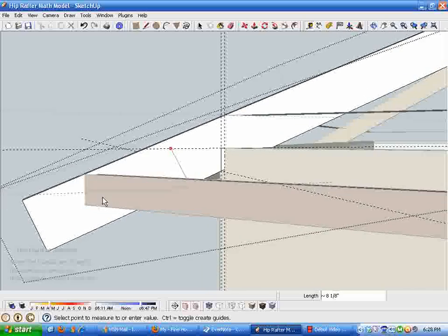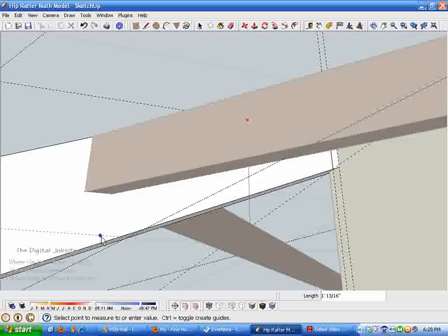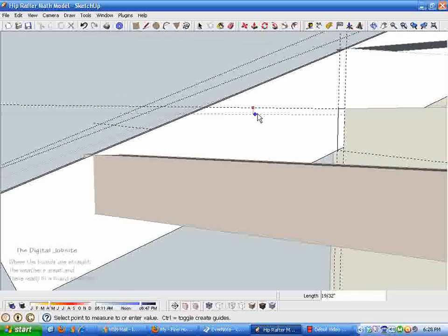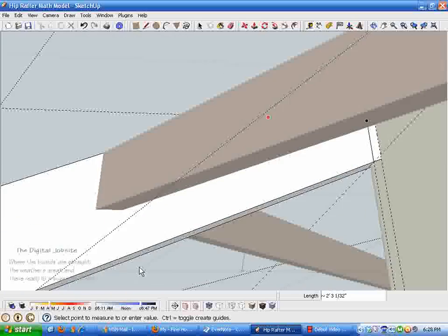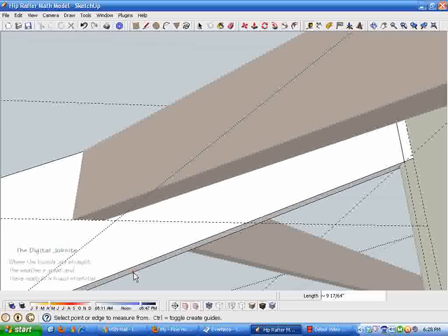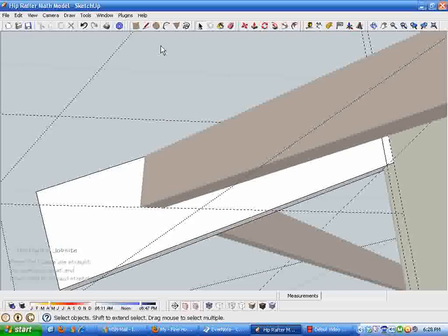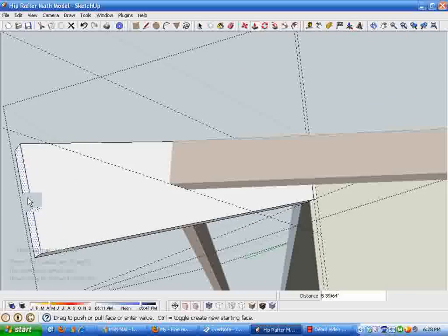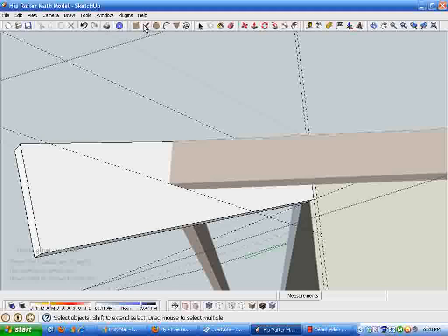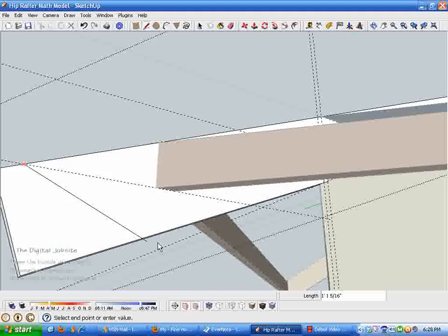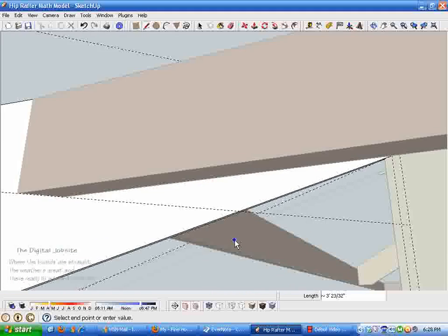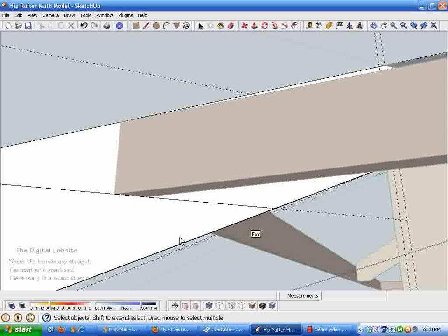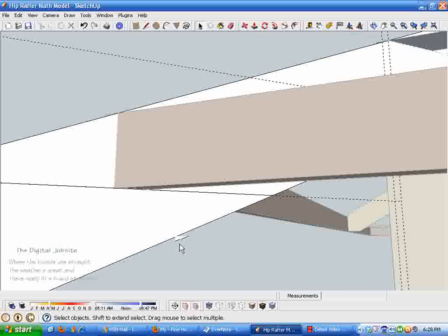And you'll notice I'm not cutting any of these things out. I'm just putting lines in here. You'll see why as this develops. Now I've grabbed the line tool again, grabbed an arbitrary horizontal line, and put it right at the bottom of the fascia. Shorten that rafter up a little too much because I want this line to go from the top of the hip rafter to the bottom. This would be the horizontal cut at the heel that accommodates the fascia.